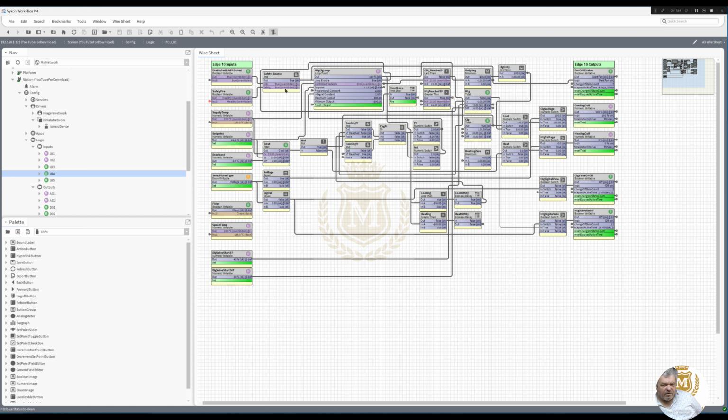Loop is enabled. We've got a supply of 23 degrees. We've got a set point of 21, so we definitely want to be doing cooling. So that's hence the minus 100 there. Fan coil enabled, cooling coil is 100%. Heating coil actually is 0.